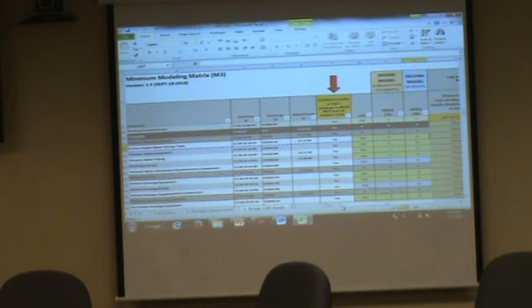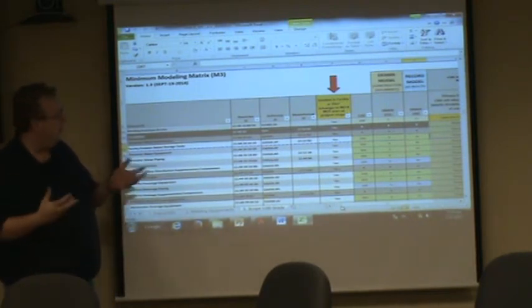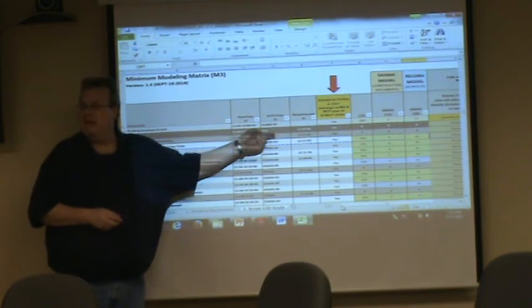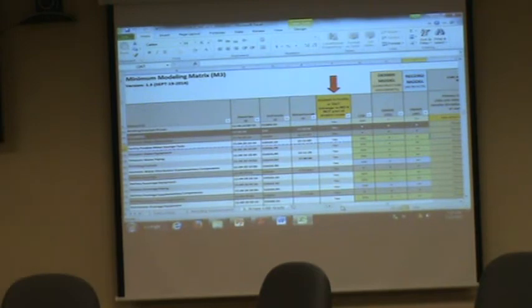It does, yeah. And how many people here have heard of OmniClass before? Well, OmniClass is the next level of master format, and that's what they use on the owner's side. It's got more specificity, goes up to level 5. What I like about the modeling matrix, in both softwares, both Revit and the Bentley side, is that if you do that for the Corps, they tell you what the classification system is, so you don't have to figure it out anymore. If you open up Navisworks and pick on a door, it's going to tell you all 3 classification systems, so you don't have to go figure that stuff out anymore. That's a big time saver, because everybody uses the model differently.